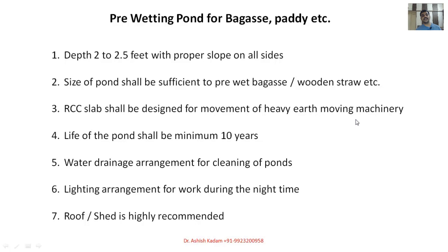So you need the right drainage arrangement, the right gutters, right slopes, and right sizes, and an arrangement even for cleaning the gutters, because you are working with agricultural material, which may jam all the water flow areas. So we need to have access points available in the gutters, etc., so that you can frequently clean them and allow the free flow of water in those areas.